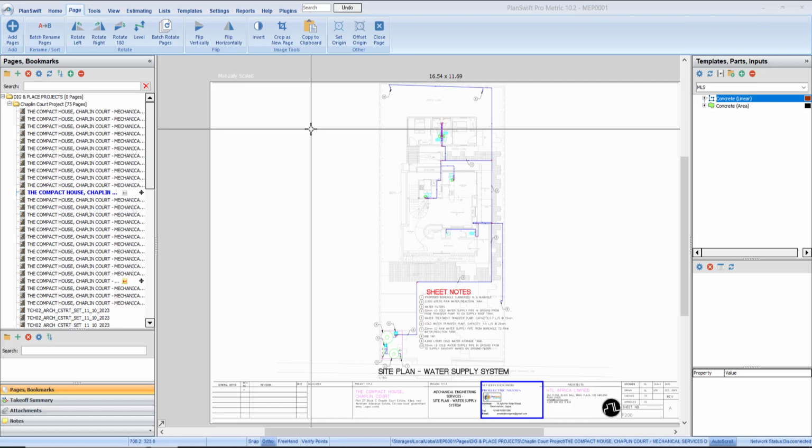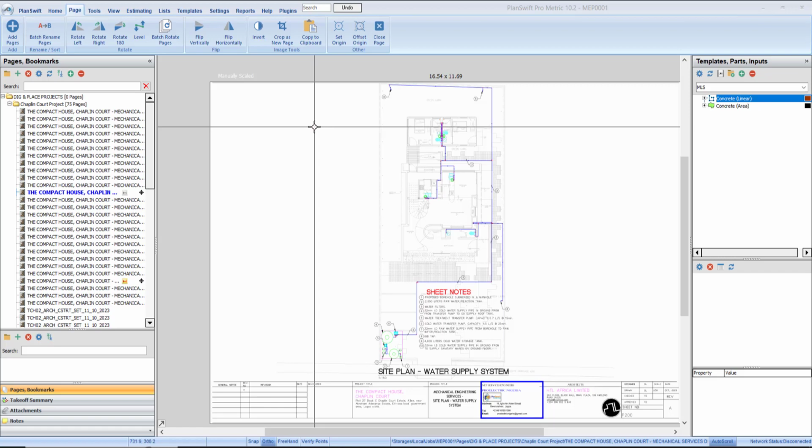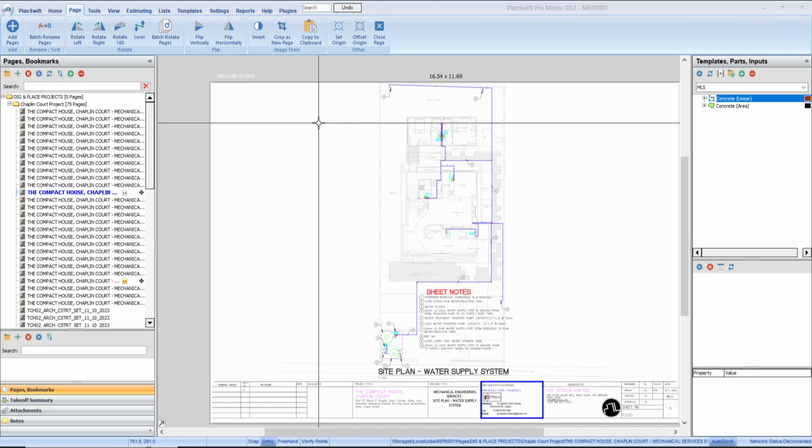Again, you have to also get yourself familiar with the architectural drawings, more especially the sectional drawings, because that is going to give you the height or the length of your riser pipes and other pipes like the vent pipes and all of that. So you're going to be able to read that drawing and then get your total length from them, even though the software will also help you do that. I will take you through this measurement and then I will combine it.